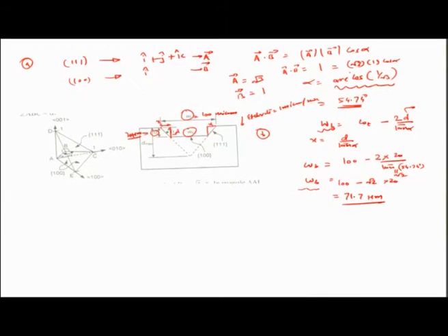The other part of the problem statement wants to find out what is going to be the total time for which the etch would proceed uninterruptedly, and beyond which the etch will stop. So obviously that's an instance when WB is 0, because now there are only 111 planes.